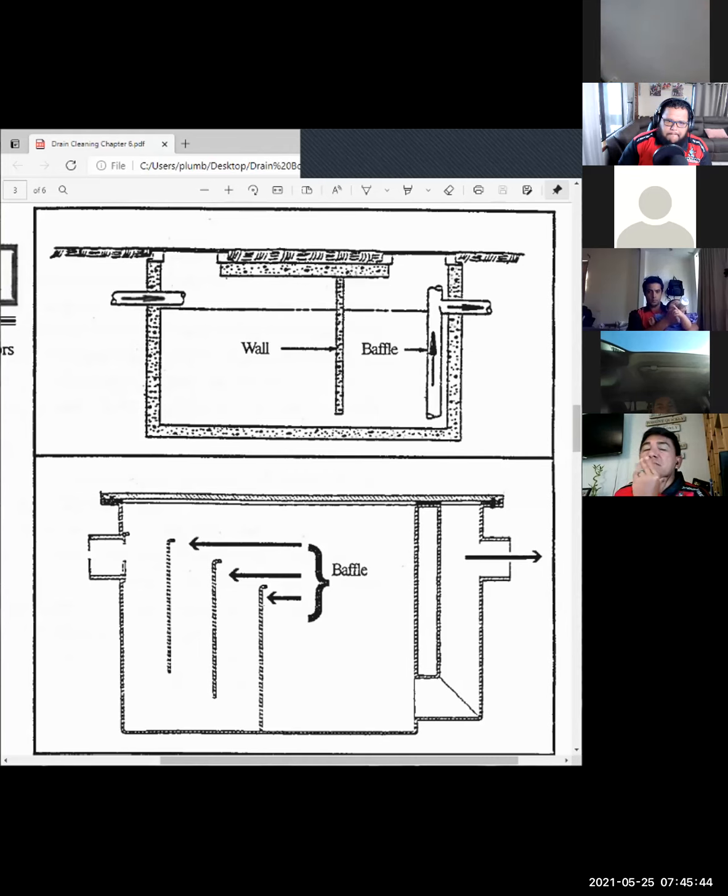But the other side of that is that this drawing makes me think it's a little incorrect. That exit should be below that water line on a mantle. Let's say that grease trap is a 1,000-gallon grease trap and it's 5 feet from exit to bottom. You can have a mantle as thick as 2 feet and still be within compliance of when the grease department, or should I say wastewater, says you have to pump it.